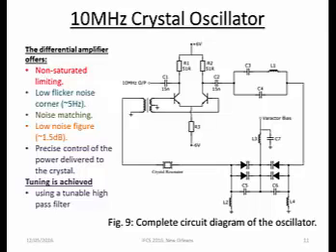This is the spurious resonance rejection filter, which is based on only 3 reactive components. The electronically tuned phase shifter uses varactor diodes and is based on a 5th order high pass Butterworth filter. And of course, we have the crystal resonator.